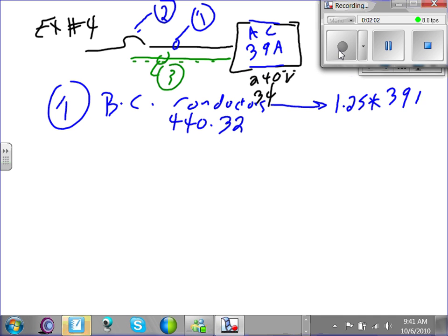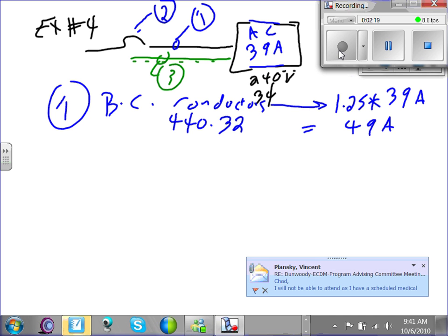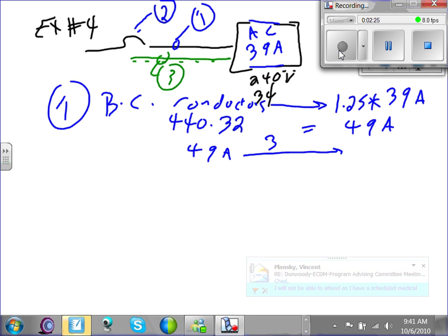39 amps. Okay, who's going to do the math for Chad? This equals 48. Even 48 amps. 0.75, that'll make it 49. Always approximate. 49 amps. Okay. Then you take the 49 amps always to Table 310.16 under.